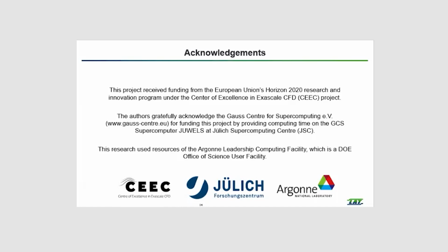Then we wanted to evaluate the performance of NekRS, and that is why we ran these cases on various HPC machines. And the results indicated that the performance improvement of NekRS is pretty much analogous to the memory bandwidth improvement of the GPUs that we utilize for each case. We also saw that we have near ideal parallel efficiency until about 2.5 million grid points per GPU, which seemed to be the strong scaling limit, because beyond that point, the parallel efficiency dropped significantly.